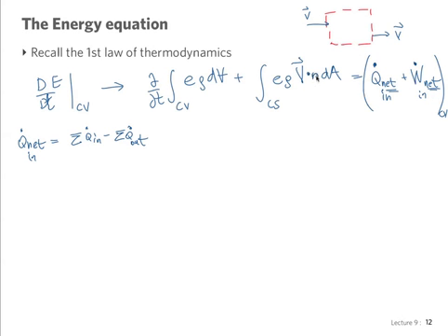This is the unit normal, as we had for the momentum equation. It's the same form that we had for the momentum equation. It indicates that there is energy going in with the fluid to a control volume, there's energy going out with the fluid, and there could be a change of total energy in the system, like with the mass and the momentum equation, the same point of view. Outward, normal to the surface.